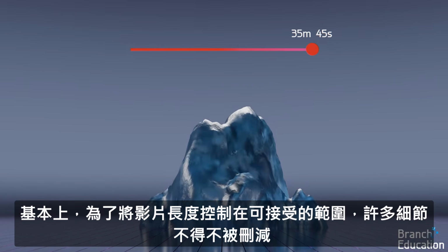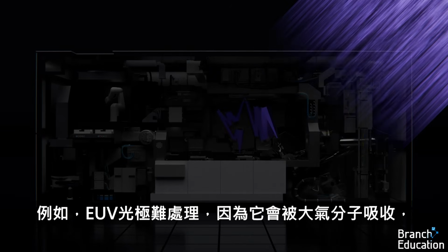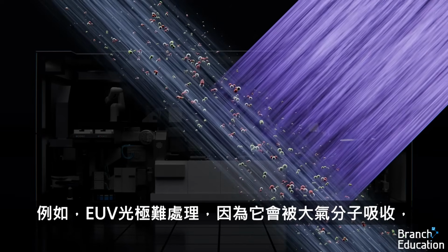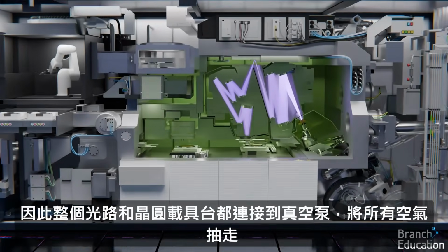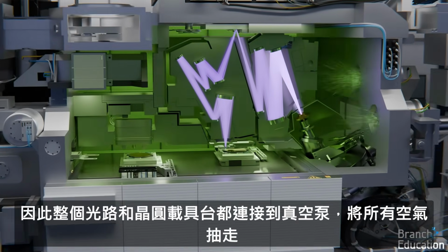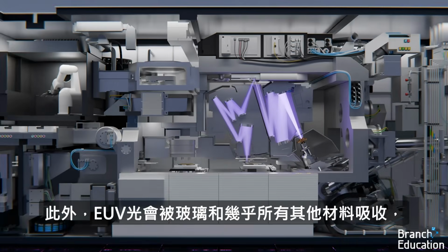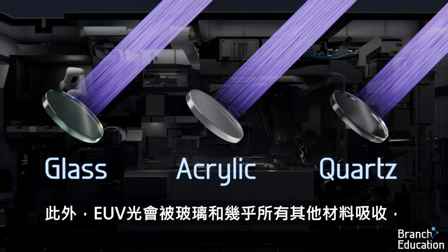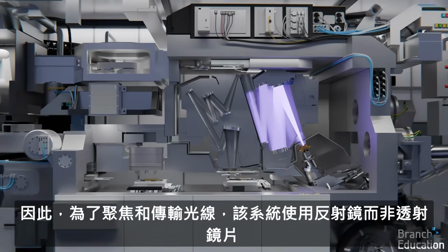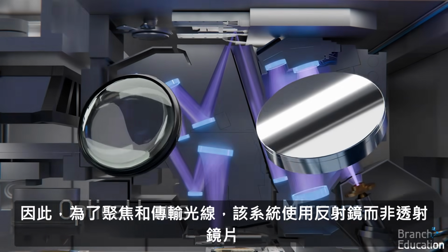For example, EUV light is incredibly difficult to work with because it's absorbed by atmospheric molecules, and therefore the entire light path and wafer carrier stage is connected to vacuum pumps which remove all the air. Additionally, EUV light is absorbed by glass and practically all other materials, and therefore to focus and transport the light, this system uses mirrors rather than transmissive lenses.